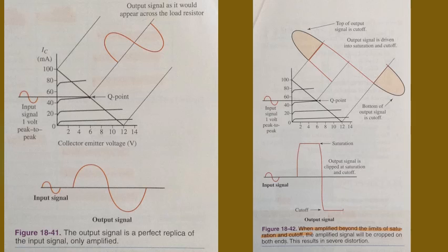A multi-stage amplifier designed for small gains of 7 to 10 has far better sound quality than an amplifier with only a few transistors with large gains of say 50. This is one reason for the large variation in prices for amplifier systems. The amplifier with many stages will undoubtedly cost more and sound better.